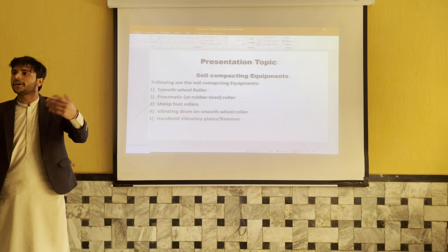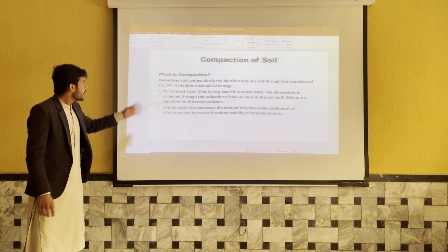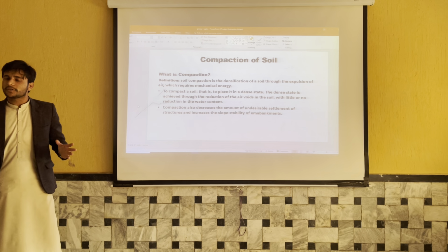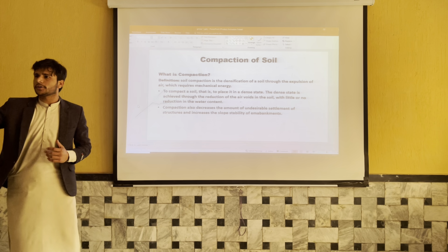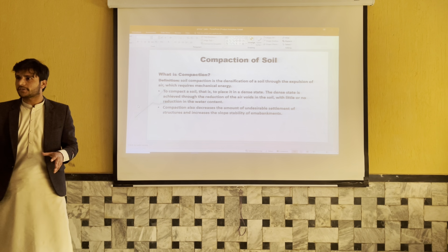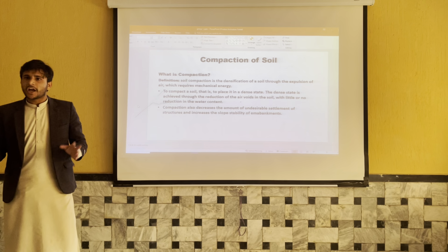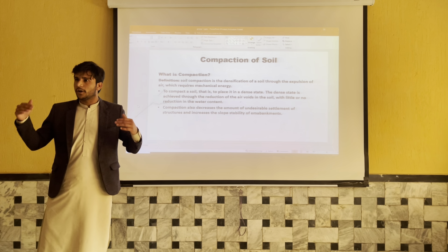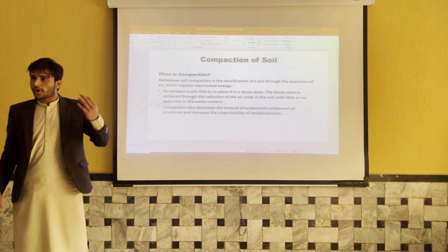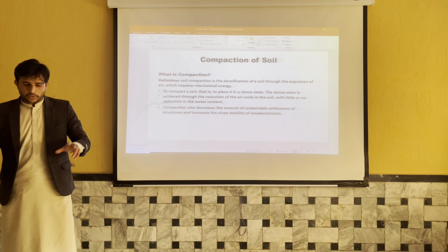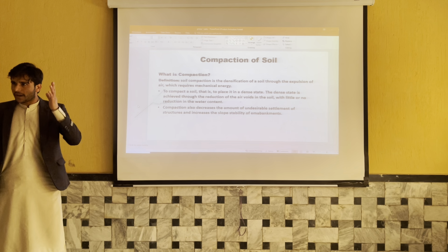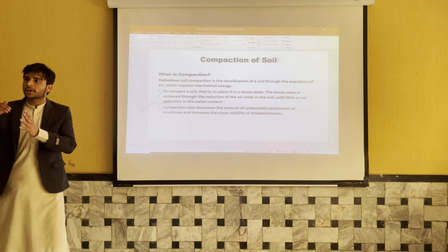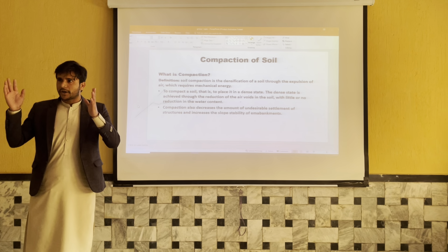What is compaction? Why is it necessary? The definition of compaction is the densification of soil by mechanical means. You can see the rollers working on the ground, so it is a mechanical way to compact the soil. Now, what is densification of soils? As we know, soil has 3 phases. It has air, water molecules, and solid particles. In between, the voids also contain air. So when we apply energy, the air is expelled, the particles close together and compact, and the soil becomes densified.